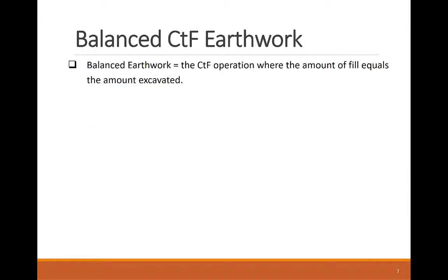Now let's define a more specific objective for CTF operations, which is trying to balance them. Balancing earthwork operations is our way of trying to achieve the number one goal of construction: reduce costs and waste. It's very common sense to try to match the soil you excavated to the areas that need to be filled, instead of hauling the excavated soil to a dump site and then buying soil from a quarry and hauling it to the site. If the on-site soil satisfies these geotechnical specifications, why not recycle the excavated soil?